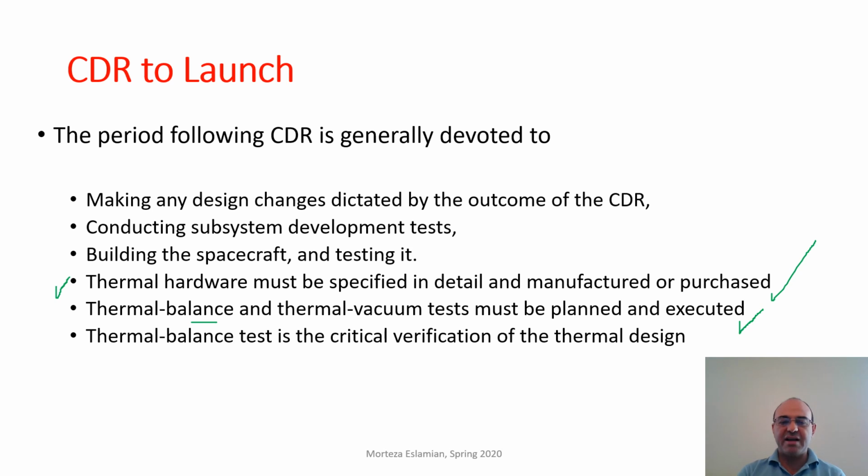The thermal balance test is the critical verification of the thermal design. We need to demonstrate that each component can operate at the actual temperature and pressure of space in vacuum and at the given conditions.